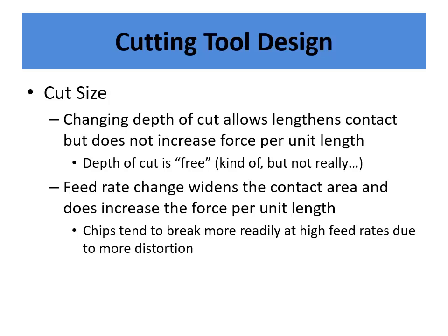So the cut size lengthens the contact, but it doesn't increase the force per unit length. Basically, if the nose of that tool goes deeper into the part, that's where depth of cut is, quote unquote, free. So essentially, if you're doing some sort of machining, you want to change the depth of cut to as deep as you can possibly cut while you're cutting. Otherwise, you're just wasting time.